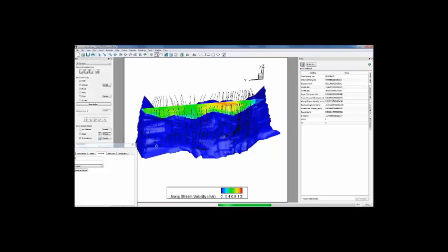One other thing is we can start to use this quantitatively. So our streamline is an integration of all of the velocity vectors. If we take something like this, and we have similar results from a model that we've developed, we now can do numerical comparisons to say how good is my model, and move some of our model calibration away from, look, you can see this is doing a good job, to where we have much more quantitative measures of how well my model is doing, and that gives more confidence when we're applying a model to look at what-if scenarios and so forth.